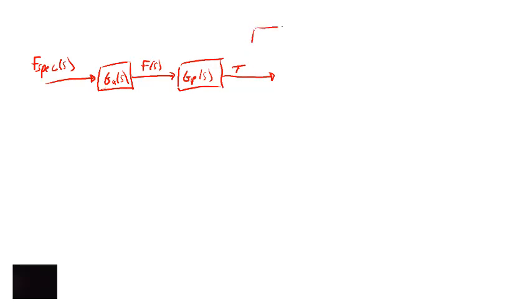We also know that we can have various disturbances to a process, and various disturbances to a process will have their own transfer function. So this will be the transfer function of the disturbance. And so this could be something like an entering flow rate or something. So we'll just call this T naught. Okay, so both of these are going to affect T. So the variable, maybe I should write it right here, it's going to be T.